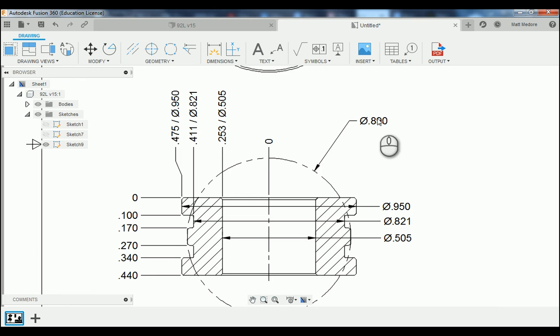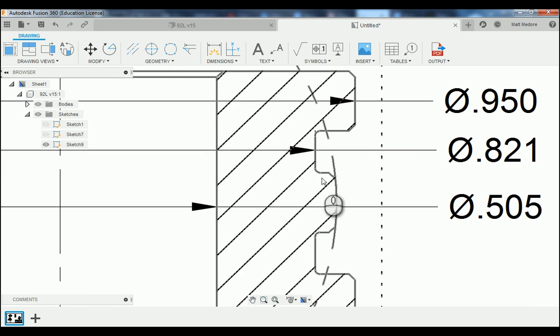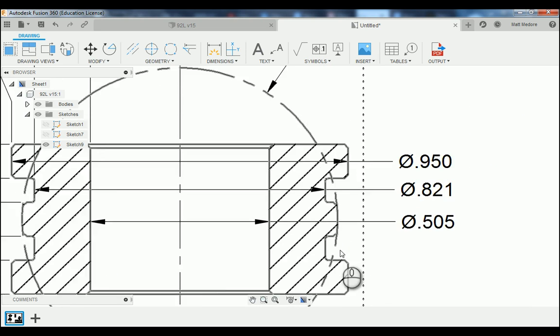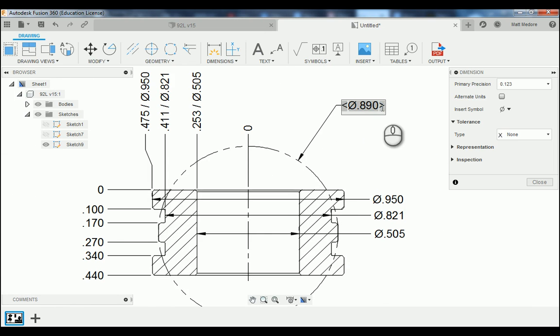Lastly, I'm going to put a little note along with this measurement. This is going to help further clarify that this construction circle is referencing off this web with this little radius here on the tip of it. I'm going to double click on this and put this note in here: circle is for web.